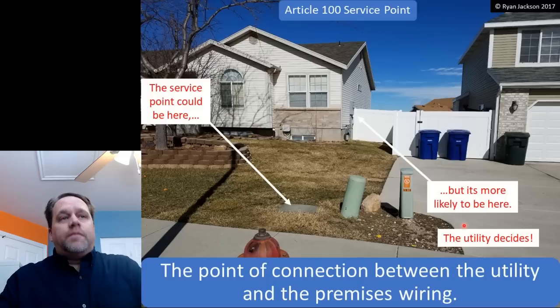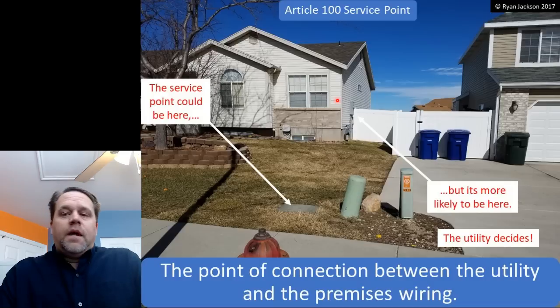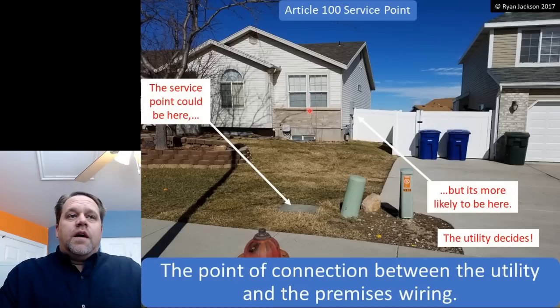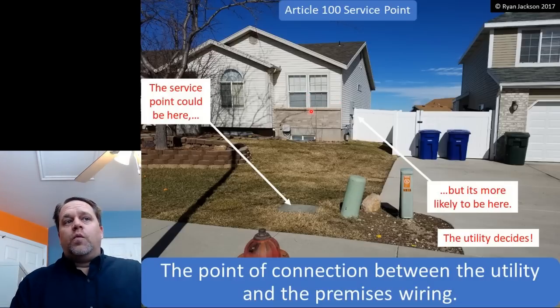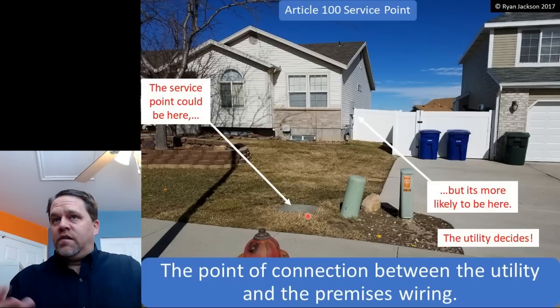The service point could be this underground junction box in front of this house, this handhole enclosure. That could be the service point if the utility said so. The utility could say, hey, look, we're going to provide power to this handhole enclosure, and then after that, you deal with it. If that was the case, then the service lateral would go from the transformer to this underground junction box. The service laterals, we know, are exempt.